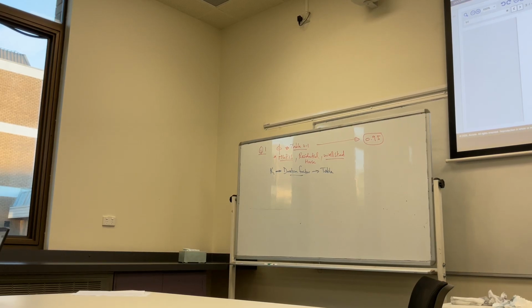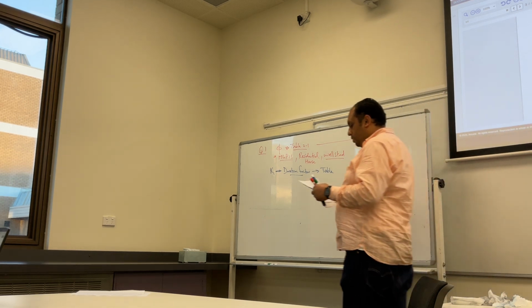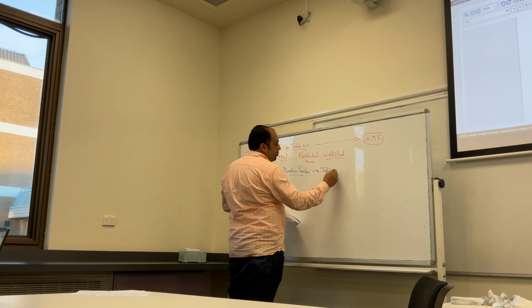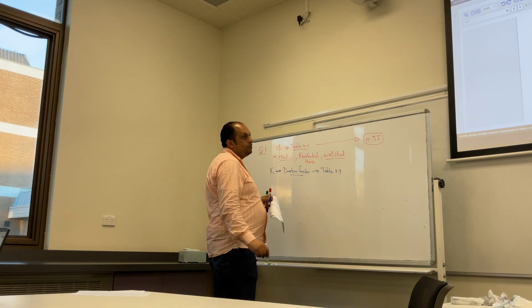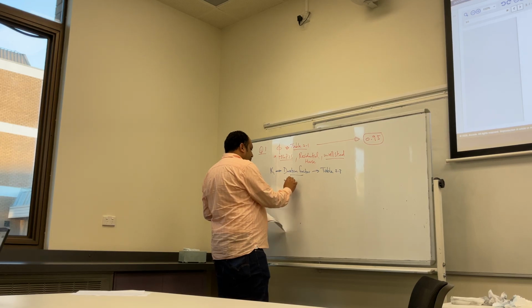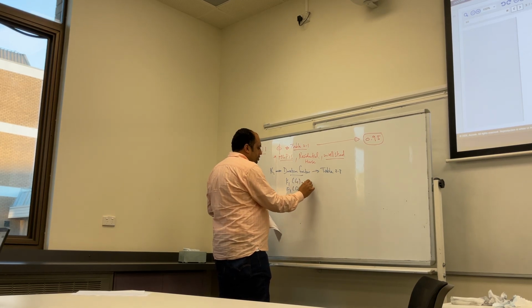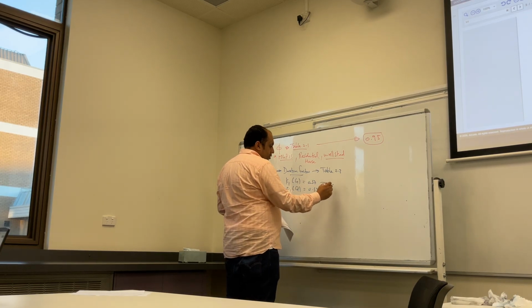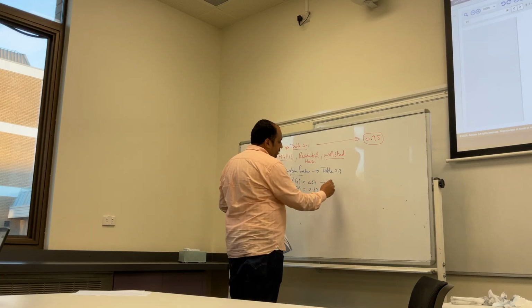He mentioned that in the load combination we have G and Q. So table 2.3: K1 for G and K1 for Q, both of them will be how much? 0.57. Why 0.57? Because both of them are 50 plus years.